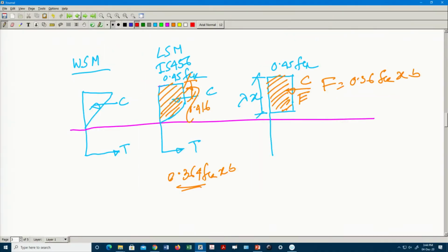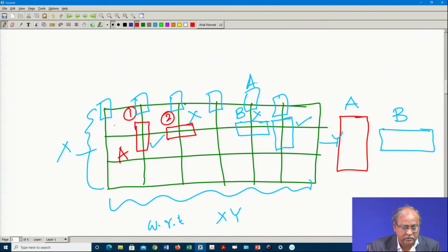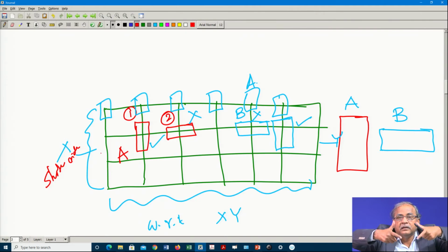For example, if the size is less on this side, it is the shorter side, so it is very easy to bend like this. In that direction, along the shorter side, you provide the column orientation.